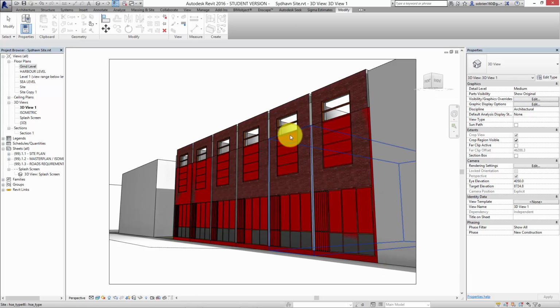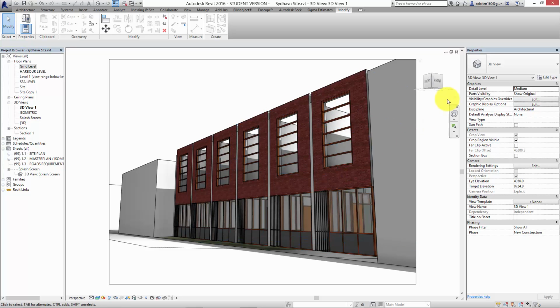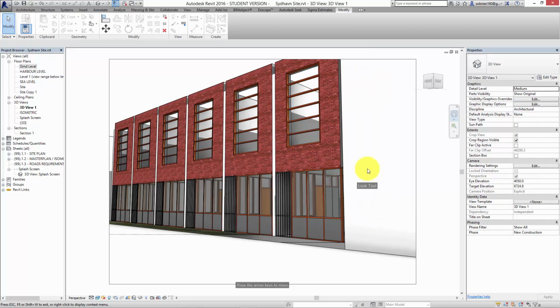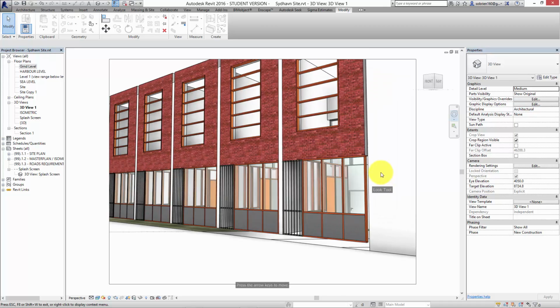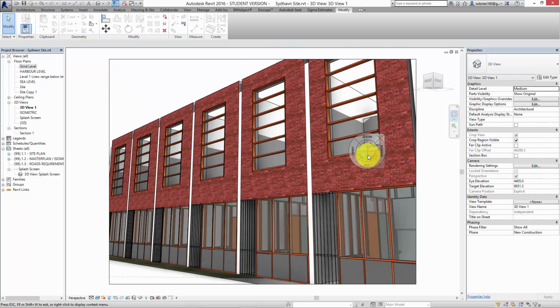Okay, so now we can just go in and delete these placeholder masses behind. And straight away, if you've been using your grids correctly, and if you've been using the placement of the linked files internal to your prototype house, they should come up with exactly the same position, but also the individual elements should be calculated in exactly the right way as well.